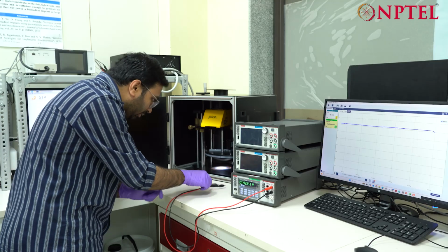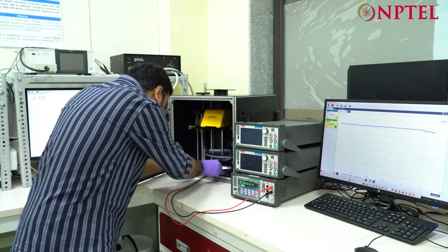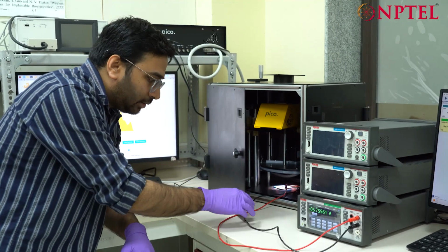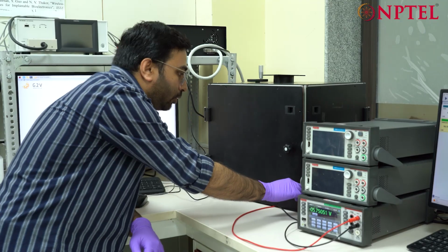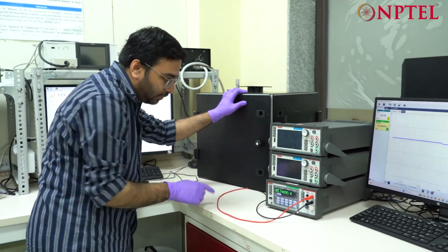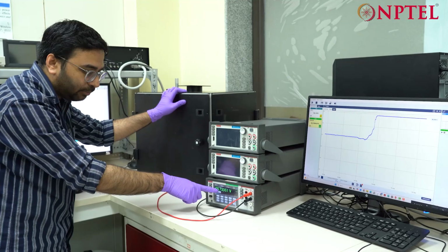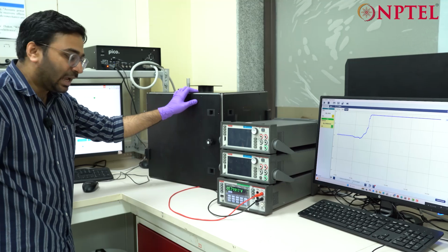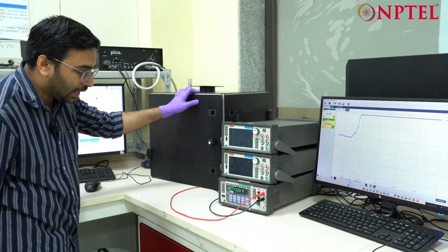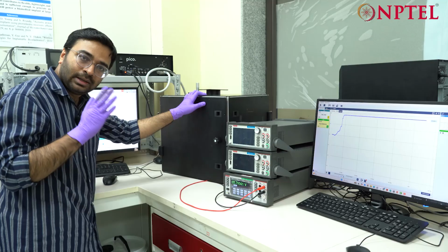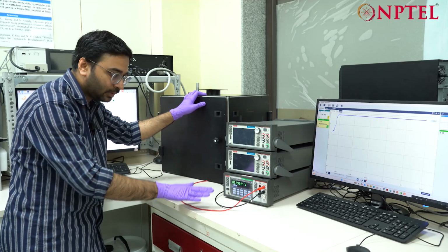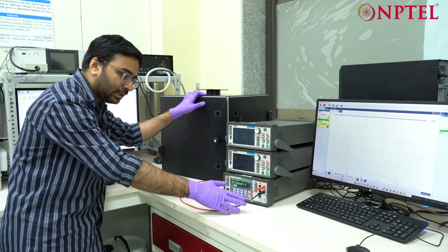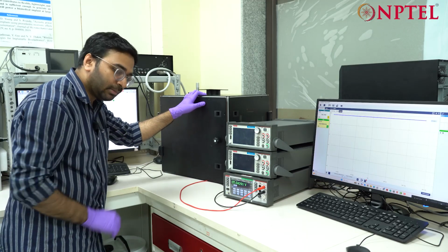Now what we will do is, we will put this particular device under this illumination here, and let us close this. Now in such a situation you get a voltage which is close to 5.7 or 5.8. So this particular voltage we get at AM 1.5, and this is a positive value, meaning the positive terminal, that is the red one of the multimeter, is connected to the positive terminal of the solar cell. The negative terminal, that is the black one, is connected to the negative terminal of the solar cell.